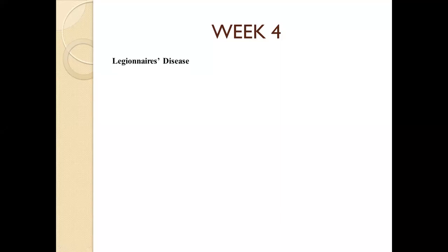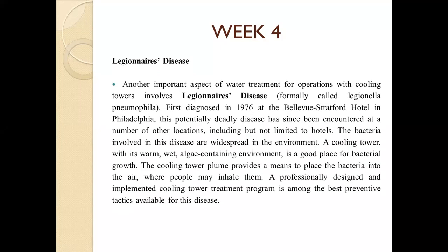Okay? Next is we have the Legionnaire's disease, another important aspect of water treatment for operation with cooling towers involves Legionnaire disease, formerly called Legionella pneumophilia, first diagnosed in 1976 at the Boulevard Sanford Hotel in Philadelphia. This potentially deadly disease has since been encountered at a number of other locations, including but not limited to hotels. The bacteria involved in this disease are widespread in the environment. Cooling tower with its warm, wet, algae-containing environment is a good place for bacteria to grow. The cooling tower plume provides a means of placing the bacteria into the air where people may inhale them, and a professionally designed, implemented cooling tower treatment program is among the best preventive tactics available for this disease.